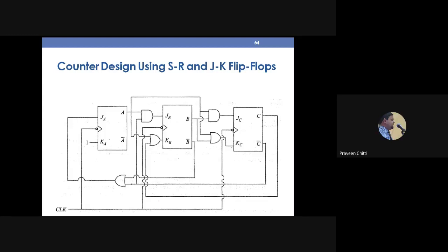All 3 are JK flip-flops, but whether we have used positive edge triggered or negative edge triggered flip-flops, that depends on what? You can see how we have shown the clock. How is the clock applied? The clock is shown with bubbles. So it indicates which edge flip-flop? It is called Negative edge triggered. Negative edge triggered JK flip-flop.